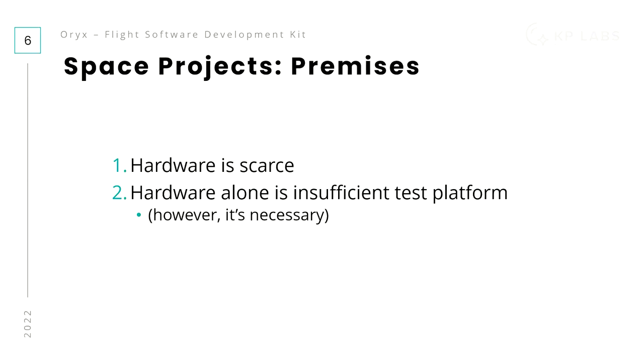And so you can compare what you see, what you get, and this is the result of the test. If you are testing on hardware, you may have trouble setting it in the correct state. For example, if you have temperature sensors and you test with actual temperature sensors and you want to test what happens in sub-zero, then you will have to freeze them every time you want to test them, which is of course possible, but it takes resources and time, and it's sometimes dangerous.